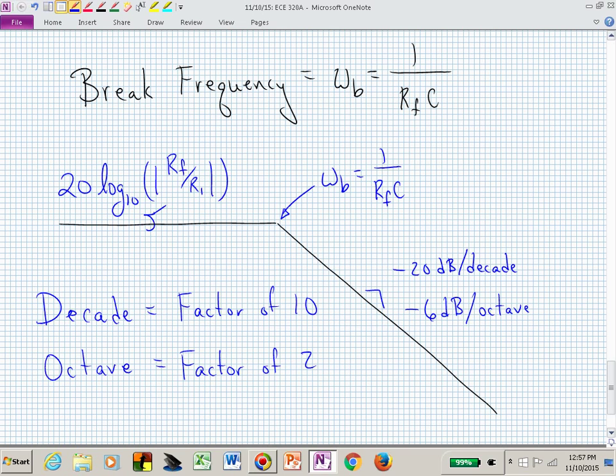Oh, where did the 20 log whatever come from? That's coming from, that's how we define dB. dB is 20 log of a magnitude. And it's really coming, if you just looked at maybe powers, you would have 10 log of something. So now the something is usually in terms of voltages. This is now just the formula for magnitude in dB. It's 20 log of this transfer function's magnitude. All right, that's circuit 3.